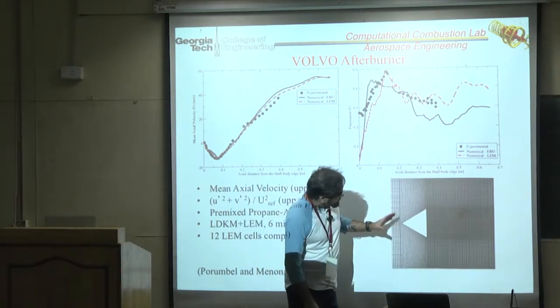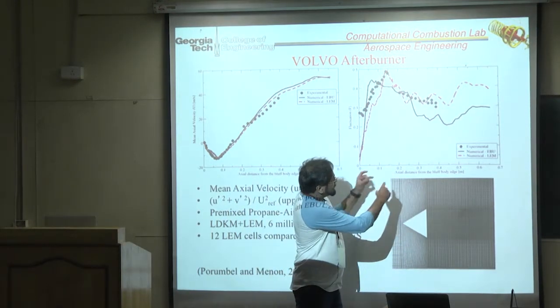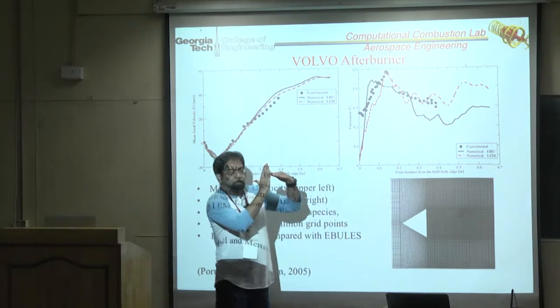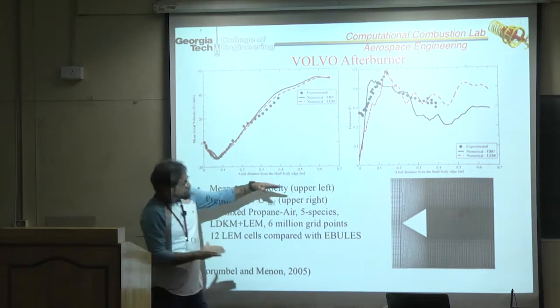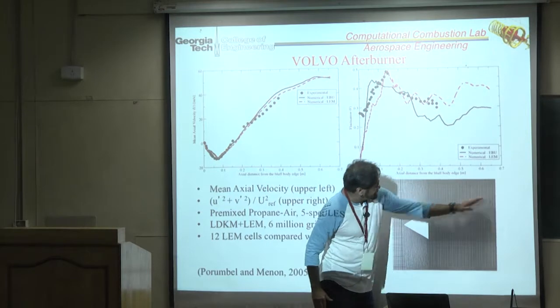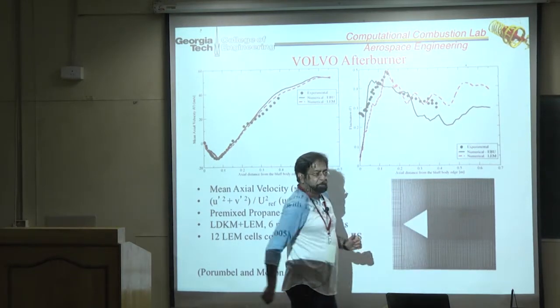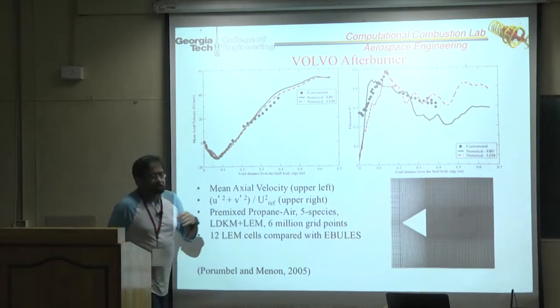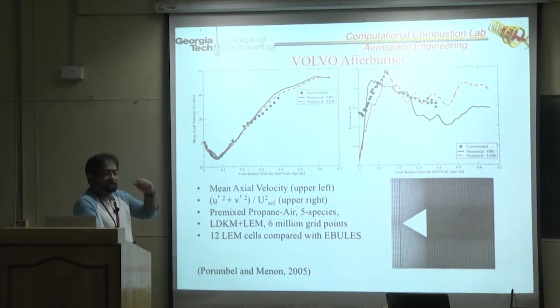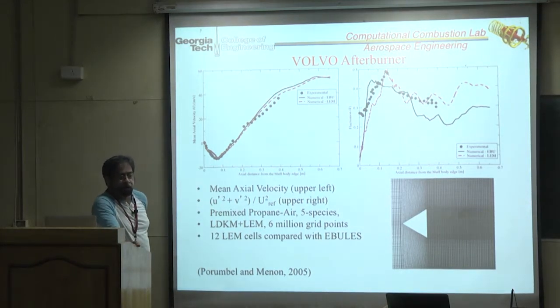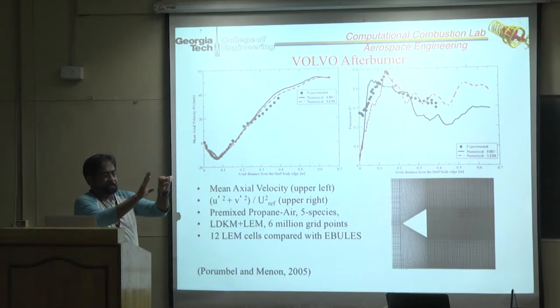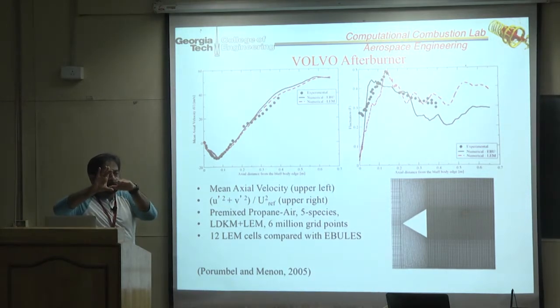So when I say coarse grid with fine grid, the grid lines will be hanging, like they disappear. Here this grid line is still going all the way. It's just a variable grid. This is a single grid. Okay, thank you. Going from grid to grid coarsely requires hanging nodes. I mean, the grid lines just disappear. So you have one grid and suddenly you have a grid twice as big, like that. Thank you.